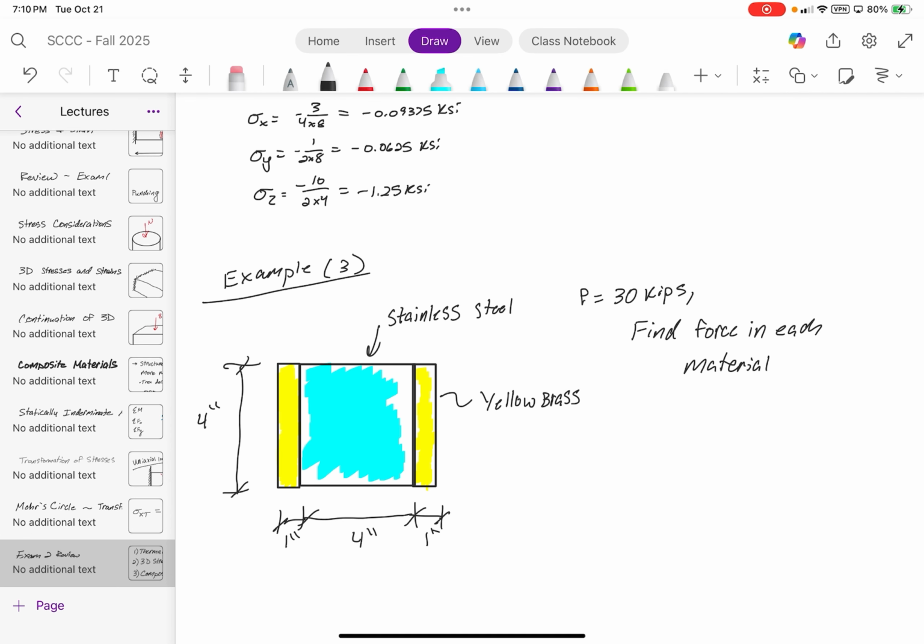But then how do the lengths cancel? Why do the lengths cancel? Just see here. When you have a vertical column, the entire cross-section is affected. Unless I give you an actual column length with different material properties, in which case you have different lengths. But if you have just an entire cross-section, the length of all the materials is the same. When you set the deformations equal to each other, the lengths will always just cancel out. Exactly. And then P_S equals P_V, and then E. Exactly. Then it's just working it out.